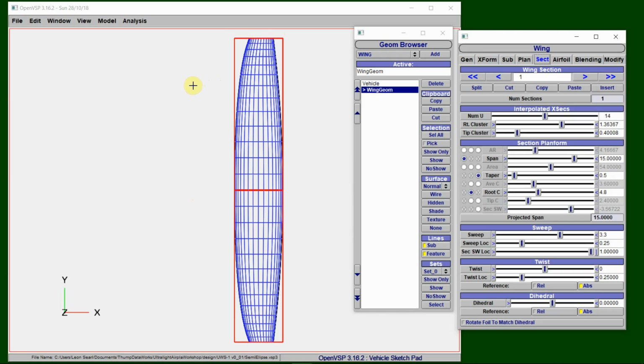But real quick, let me tell you what I like about this. I'm giving some thought to having a full span flap along the back edge. So I wanted to have a trailing edge that wasn't too curved. A little bit of curve's fine, but I didn't want to have significant curve because I'd like it to be a one-piece flap along the back edge. There is some curve, but that's certainly tolerable. I instead switched the curve to the front edge.